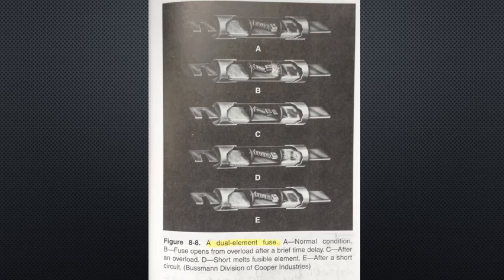In renewable fuses, the fuse link can be replaced. This allows the fuse holder to be reused, reducing cost. A non-renewable fuse, one-time fuse, must be discarded after use and can be replaced with a new fuse. Current limiting fuses quickly open the circuit when a specified overcurrent is reached. These fuses clear the circuit of currents in a fraction of a second.